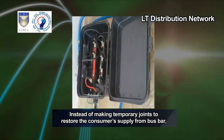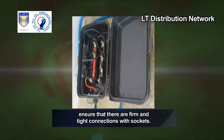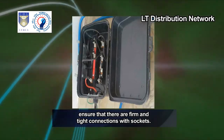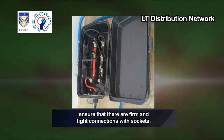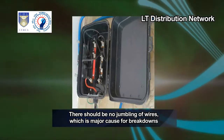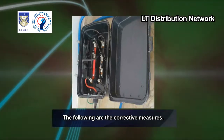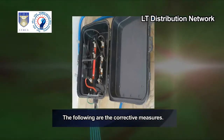Instead of making temporary joints to restore the consumer's supply from bus bar, ensure that there are firm and tight connections with sockets. There should be no jumbling of wires, which is major cause for breakdowns due to loose and temporary connections. The following are the corrective measures.